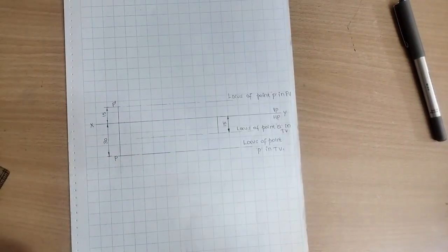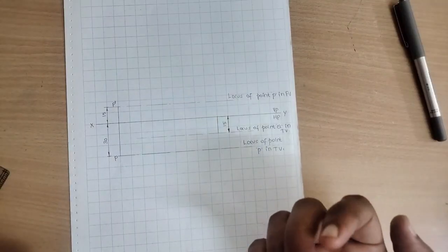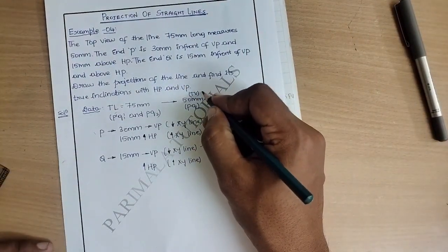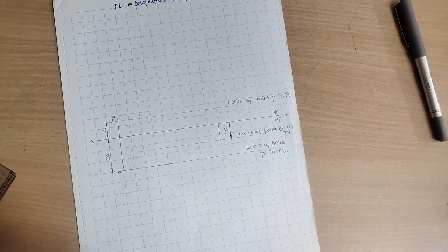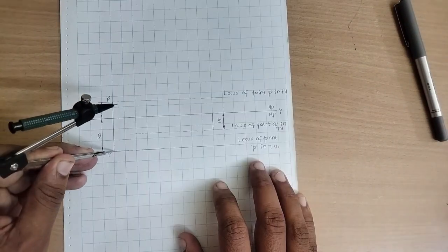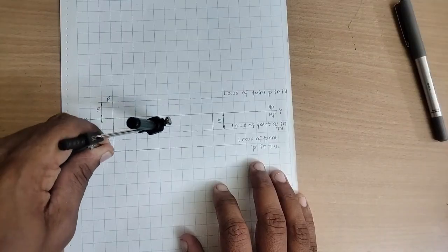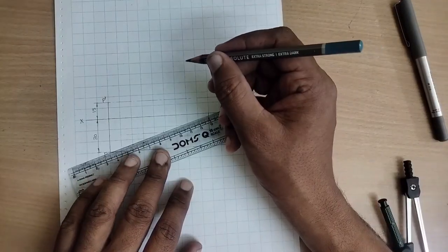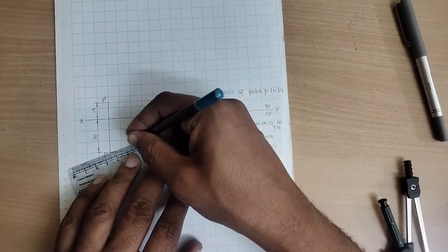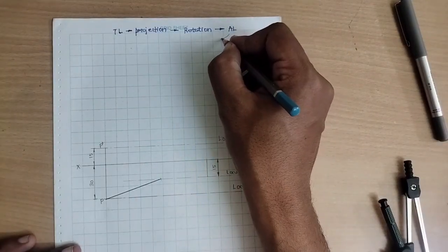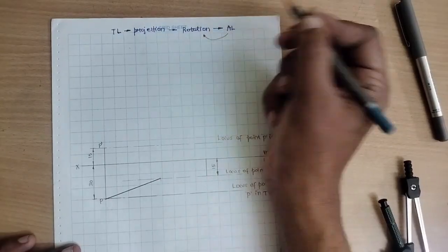Now, I have a true length and I have an apparent length as well. I will start from the top view data, that is 50 mm in the top view. Make use of your compass. Take 50 mm, 5 grids. Point P as the center, let us cut an arc on the locus of point Q, something like this. Since this is the apparent length, let us increase the thickness of this line. Apparent length is ready.